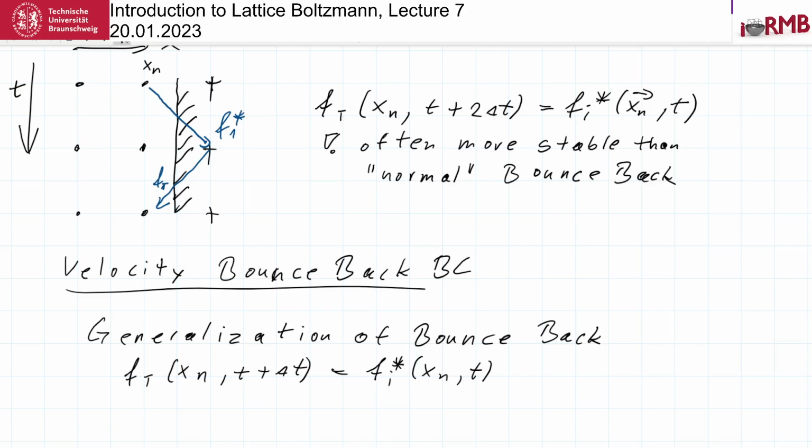And then we add a modifier on the velocity, which is 2 theta, the lattice weights that we know from our BGK collision operator in the equilibrium. And this we multiply with the lattice vector. Now I write it only with one index here, so you can write it also with multiple indices. Scalar product with the velocity that you want to impose at the boundary.